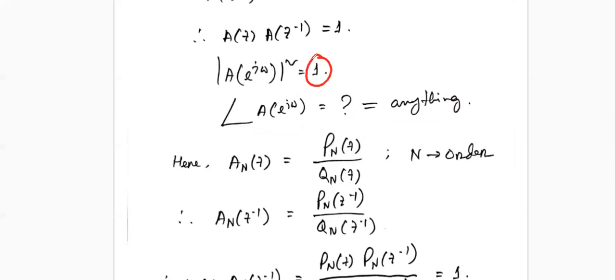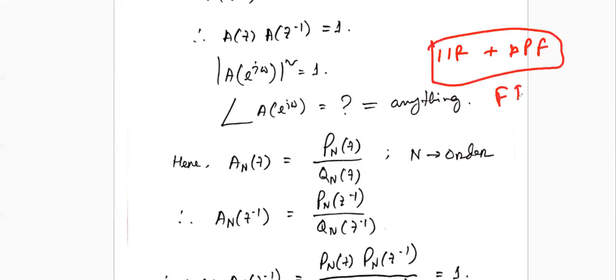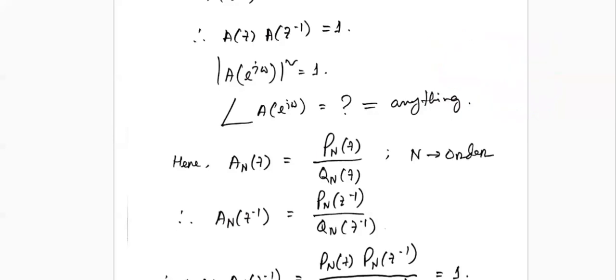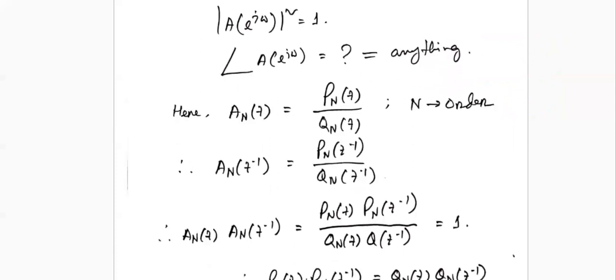It will pass everything, but you can tune or fabricate the phase of that filter so that an IIR filter, then an all pass filter can work like a FIR type filter. That is our purpose. So an all pass filter is one kind of IIR type filter because it produces a nonlinear phase.